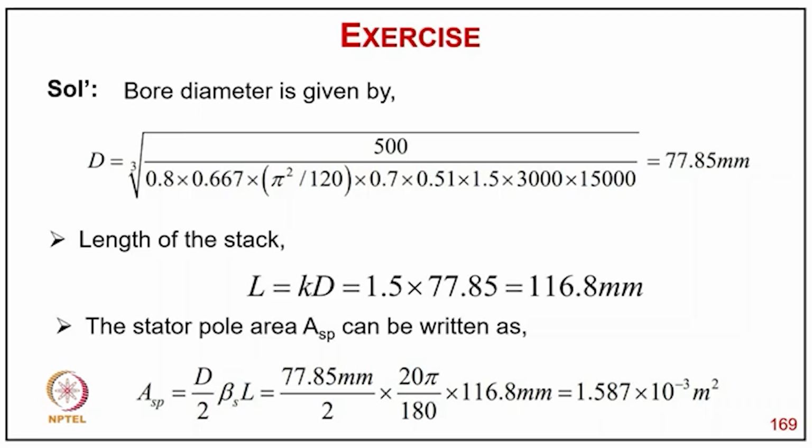Stack area: the bore diameter D, calculated as the cube root of this, comes to 77.85 millimeter. Length of stack L equal to KD, that is 116.8 millimeter.